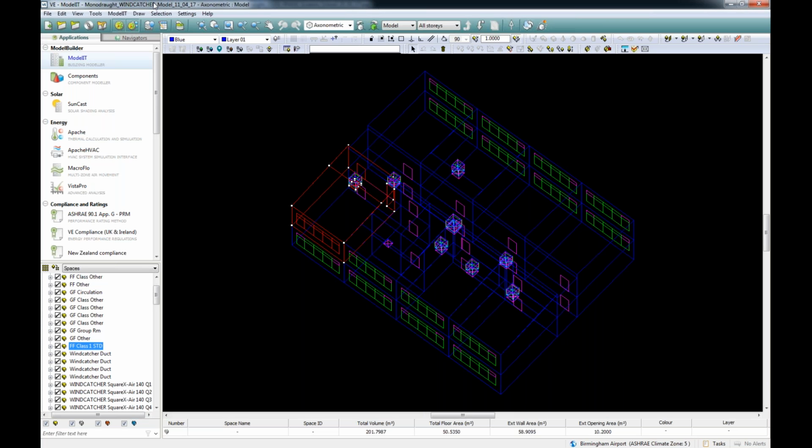But it should be noted that the room heights will have taken account of the size of the system. If you have, say, a 2.5 metre size system, you won't want a really large, say, 1 to 1.5 metres squared system serving that particular room, because you can get a lot of airflow in a small space. And our recommendation would be to have a larger quantity of smaller systems, so you're getting a better distribution of airflow going through.